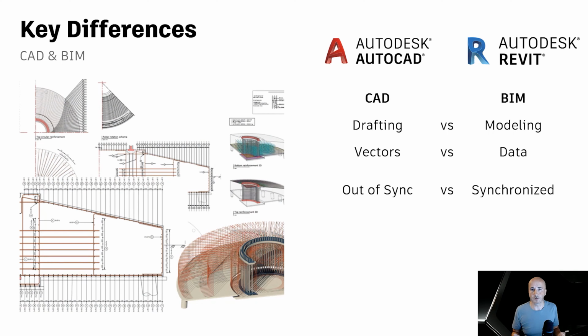It is important to understand that in Revit, these views are not separate drawings, but simply different ways of looking at the same model. At a glance, it may seem that AutoCAD and Revit approaches are similar, but the result is completely different. The use of a model-based approach in Revit means that when a change is made to any view, the change is immediately reflected in all views.